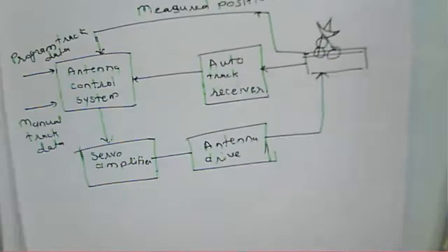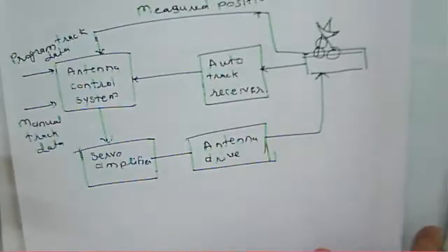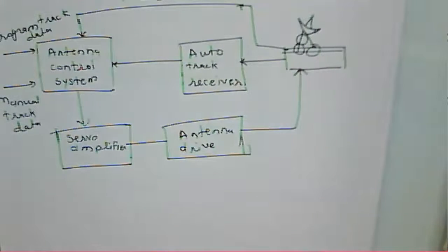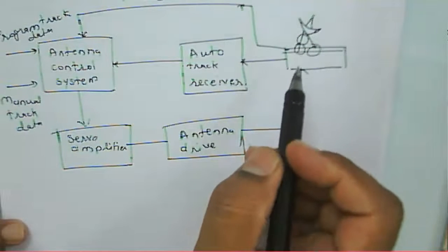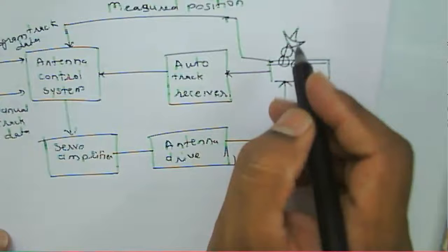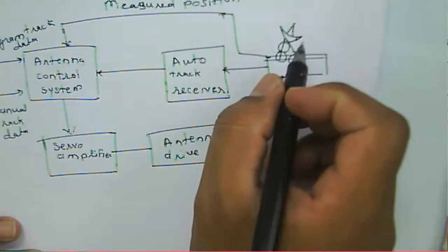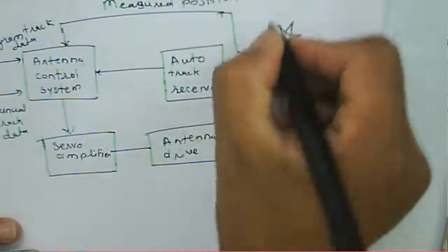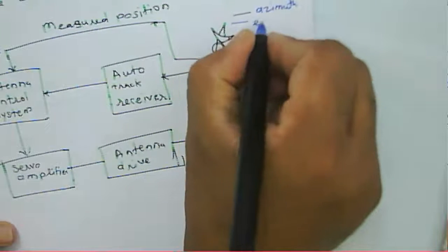Now, if you consider the basic here, it has some various motors, so we can track the satellite, and then according to that, the Earth station is to be moved there. It means that the Earth station antenna we mentioned earlier is to be a steerable one. That antenna is to be steered in azimuth or elevation. So we have two scopes here: we can rotate the antenna in azimuth, or in elevation.